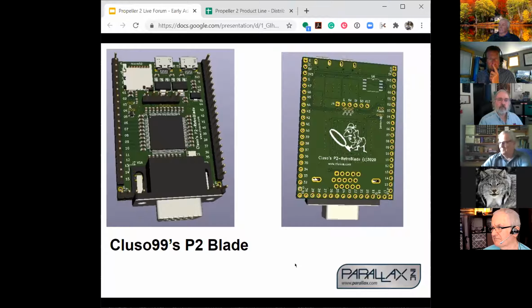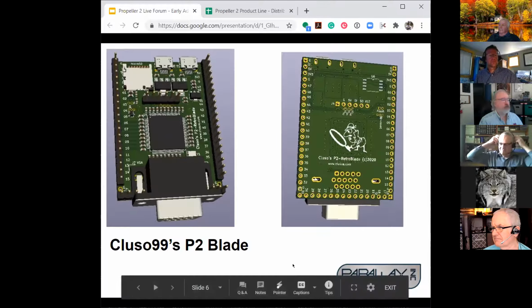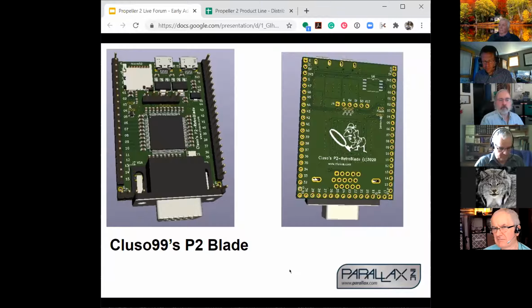Brian, if you were just doing it manually, say you had a code loop talking to a pin set up in a standard DAC mode, then you could set multiple pins using a pin group into that same DAC mode. When you do the WX, the write X command to update the DAC level, you do it to the pin group, and all of them would be updated simultaneously to the same value.